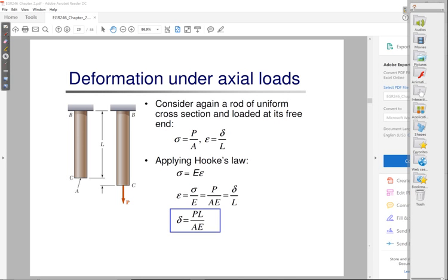Okay, find me the length. Okay, so that might be a design problem. Another variation is, I've got a 1 foot long steel rod for which I'm going to apply 500 pounds. I don't want it to deform more than 0.001 inch, right? How large should I make the diameter? Or what's the smallest I can make the diameter?